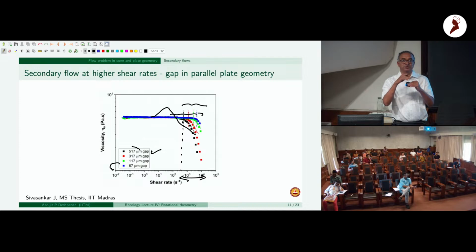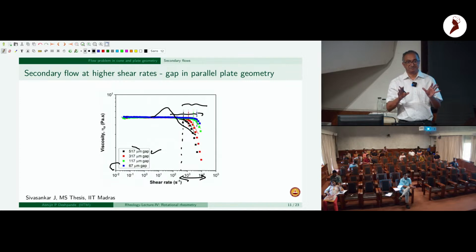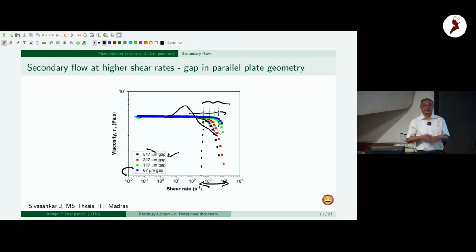So initially you do your analysis with an order of magnitude gap just to see whether qualitatively you are getting the same feature. Then you do it in a much narrower window to ensure that it's quantitatively also similar. Then you say that at least in the 400 to 600 range, I am getting quantitatively the same response. If I go to too small a gap, maybe there are material artifacts. If I go to too large a gap, maybe there are inertial effects. So that kind of analysis you may have to do.